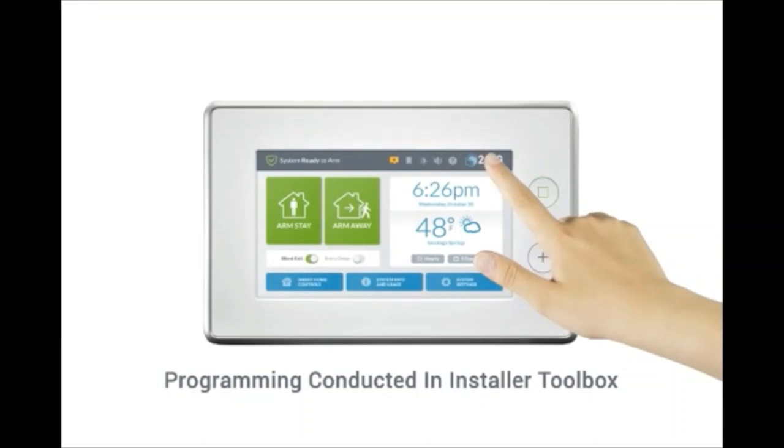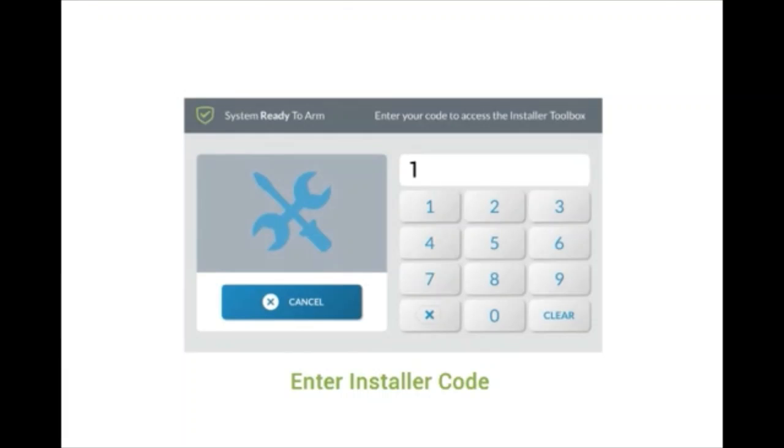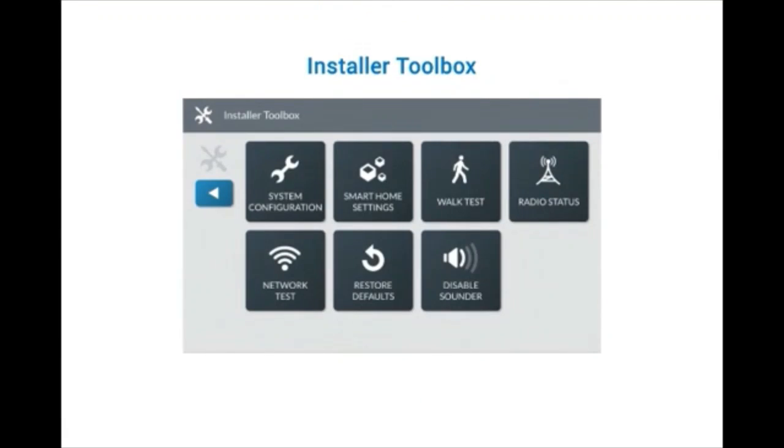To begin, press the 2 gig logo. Enter the installer code 1561. To configure and test the system, the installer toolbox offers various tools. The security sensors, features, and options are programmed and configured within System Configuration. Z-Wave devices and settings are programmed and configured within Smart Home settings.